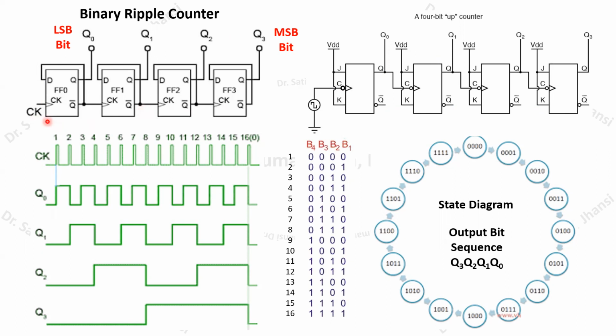So in this counter circuit using the D flip-flop, first we have to assume a certain output at Q, and then go through how the output is going to change. Once we apply the clock, at the positive edge of the clock, this is your edge and this is your level, so it is positive edge triggered. Whenever the positive edge appears, when the clock goes from 0 to 1, the transition of the output takes place.